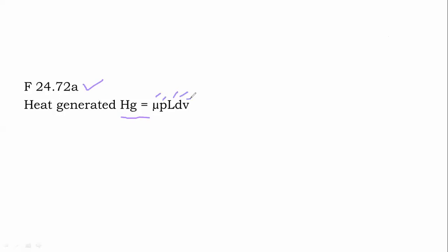So we need to calculate the heat generated, and then equate it to the heat dissipated. No artificial cooling means whatever heat is generated is equal to the heat dissipated. We calculate the heat generated and the heat dissipated, then in the one equation viscosity will be the only unknown, which we can calculate. Let's calculate all these parameters.